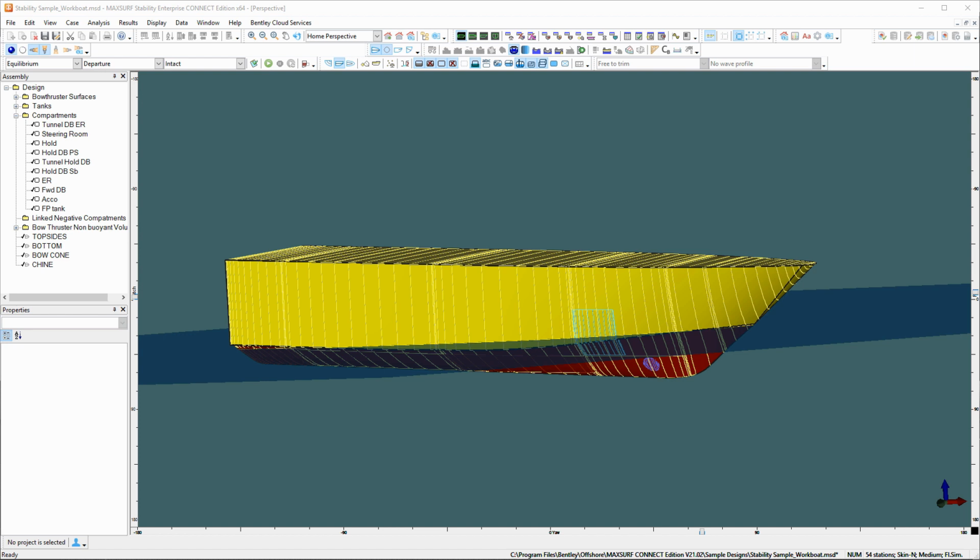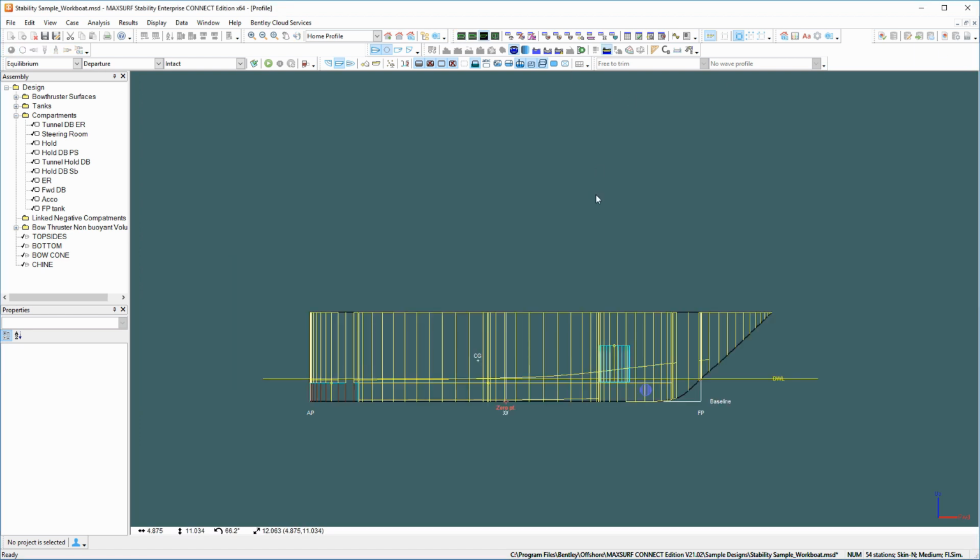I really like a limiting KG analysis for early design, where you can define an immovable limit on how high that center of gravity can go without changes to the hull shape, or if you're limited by a damage case, without changes to your internal configuration. You cannot get the VCG higher than what you find in the limiting VCG case. So it draws a very firm line in the sand that you can use with the other engineers as a do not exceed weight and height.